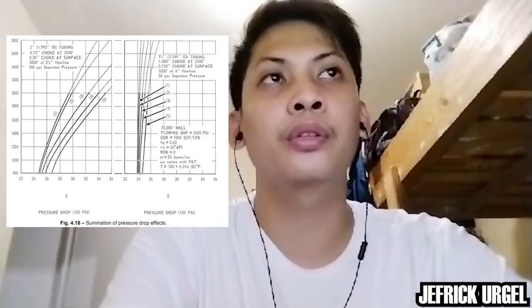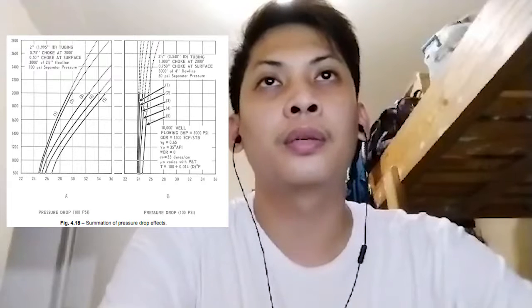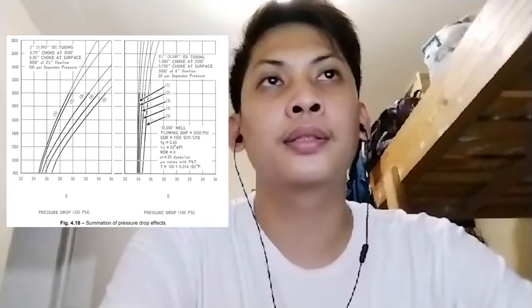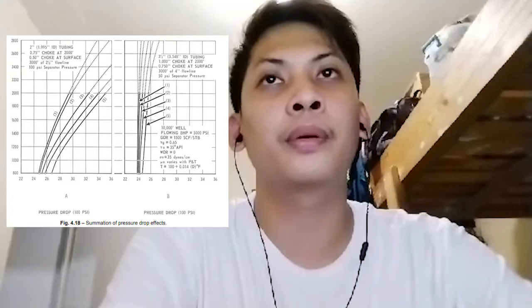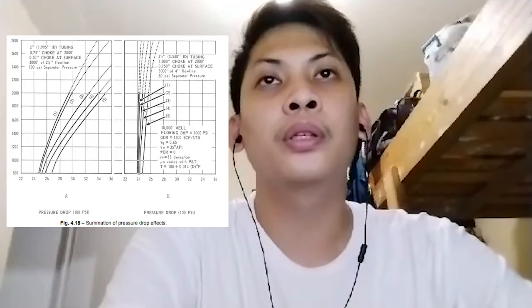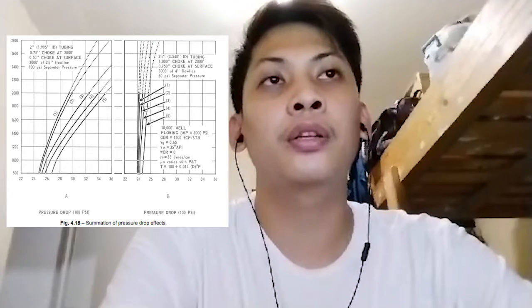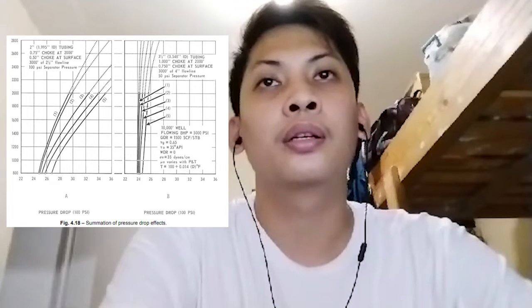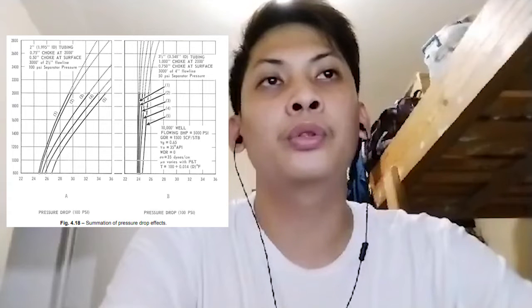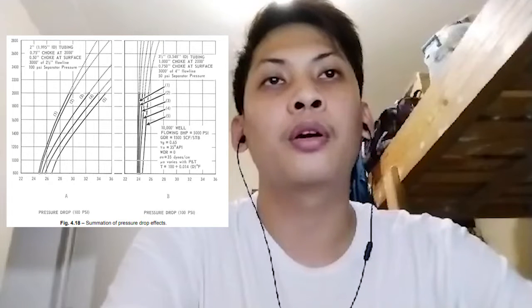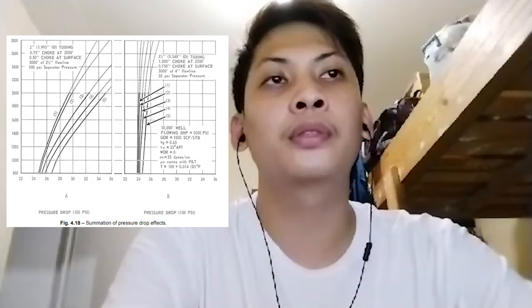The figure presents a step-by-step summation of pressure drop effects for two different equipment systems. Reservoir parameters are identical in both cases. Flowing bottom hole pressure is constant at 5,000 psi. In both situations, curves 1 through 5 indicate the same values. Curve 1 depicts the impact of tubing size and length on the pressure drop at different flow rates. Curve 2 takes into account the impact of both tubing size and subsurface choke size. Curve 3 depicts the combined impact of tubing diameter, subsurface choke diameter, and surface choke diameter.